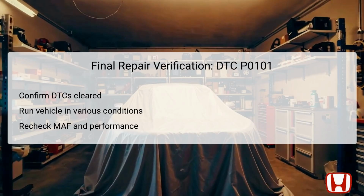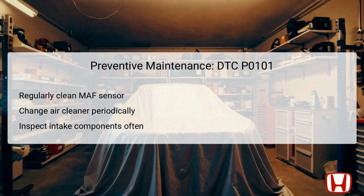Next, it's advised to run the vehicle under various driving conditions to ensure that all system components are functioning as they should. Recheck the MAF sensor and monitor performance metrics to confirm improvements. This final verification step is crucial to ensure that your repairs were effective and can help prevent any recurrence of the P0101 code.